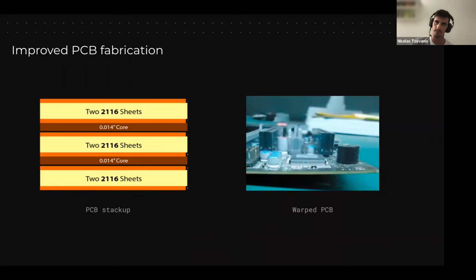So how ground fields, or any copper field in general, but in this case ground field, how it helps: it makes the distribution of copper even everywhere in every layer. So when everything gets hot and then cold back again, everything expands and shrinks in the same proportion, so the PCB stays as flat as possible.